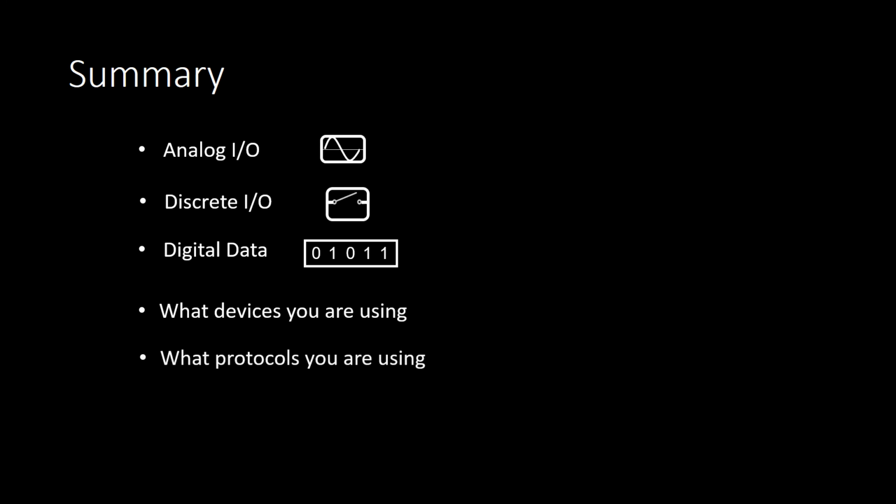What protocols are being used? Not all protocols can support I/O messaging, which means that they will need to be configured as client-server communication. Whether or not you have access to the PLC program. To use I/O communication or set up a gateway as a server, the PLC code will need to be changed.